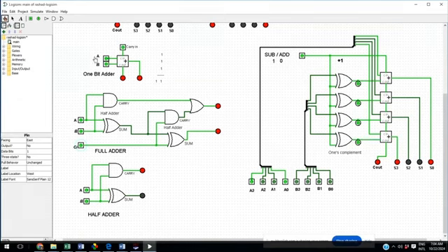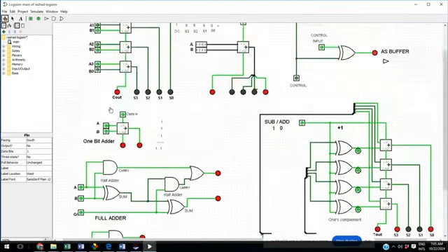This circuit can be built and combined together in one block, and this is the 1-bit full adder, with A, B, and CIN from the top, carry in, and there is a sum and the carry as well. As you can see here, you can implement the same things there. Sum 1 and carry 0. If we have 1 at A, 1 at B, then the sum is 0 and the carry is 1. If we add the carry in, then it is going to have 1 plus 1 plus 1, which is sum 1, carry 1.